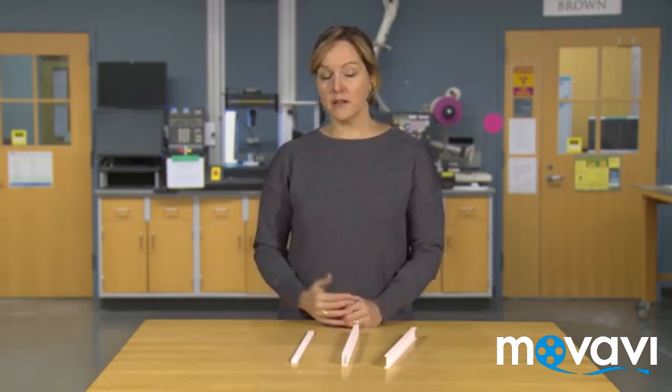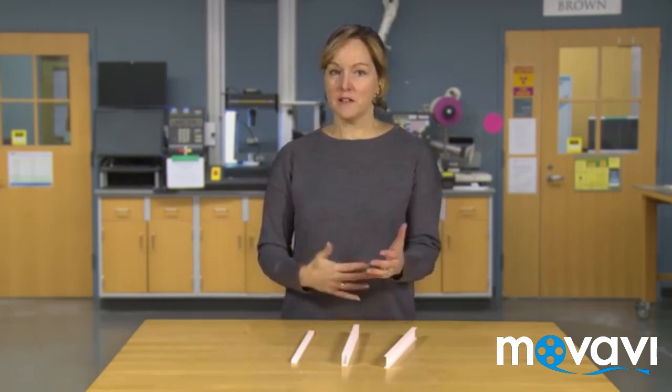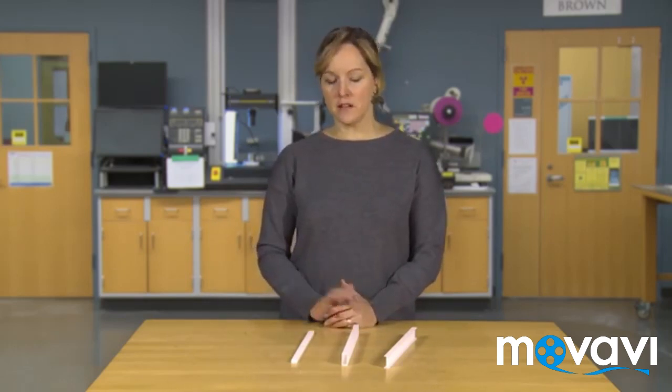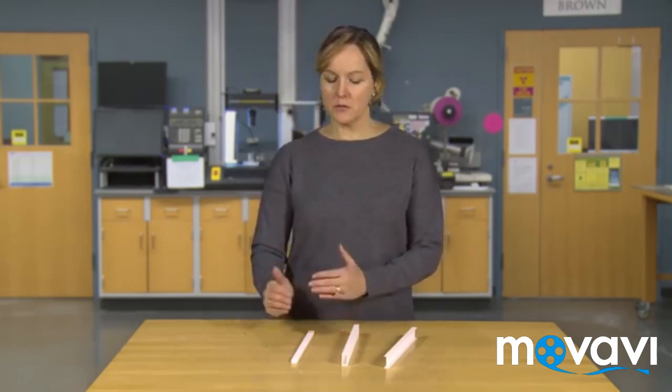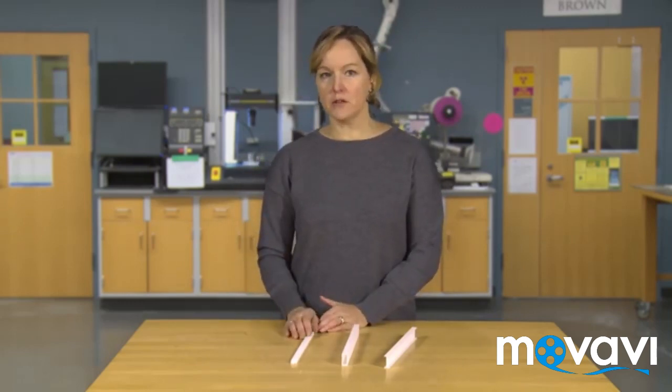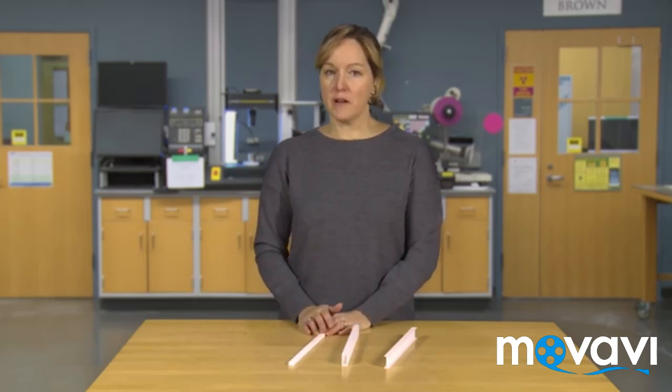That to me is somewhat counterintuitive. It seems like a wood beam and a steel beam shouldn't have the same forces. They do end up having the same forces, at least as long as they're statically determinate beams. Statically indeterminate beams would vary slightly, but that goes a little beyond the course. But even those don't vary all that much.